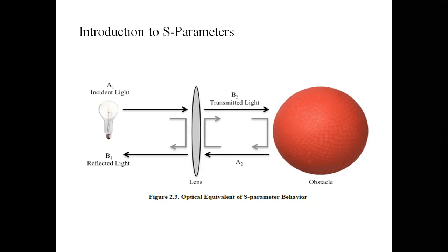The S parameters describe the magnitude and phase relationship between the incident and the reflected waves, and they are numbered according to where the wave originates from and where it is propagating to. The term scattering parameters comes from the scattering matrix, which is described in a 1965 IEEE article entitled "Power Waves and the Scattering Matrix."